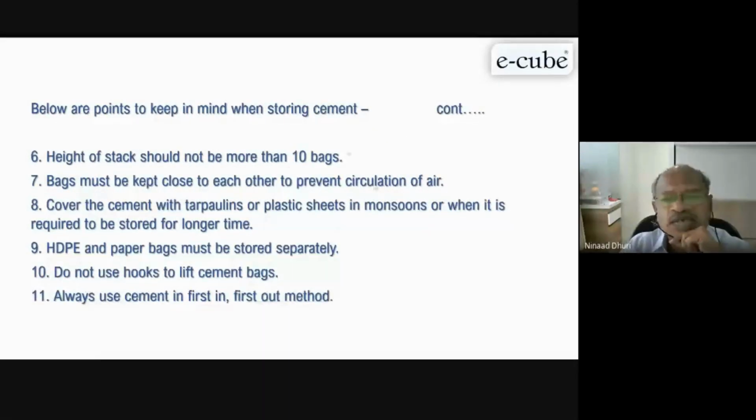Maximum we can store 10 bags in one row, one column, and they should be very close. There should not be air circulation within the bags. SDP bags or paper bags must be stored separately. Do not use hooks to lift the cement bag. Always use the cement which comes first, first out. This is the rule you have to follow.